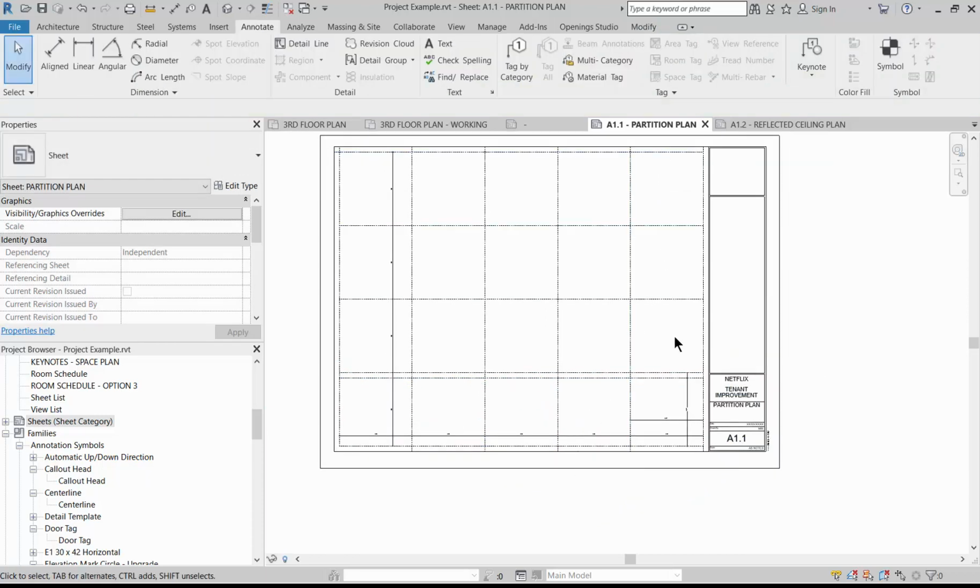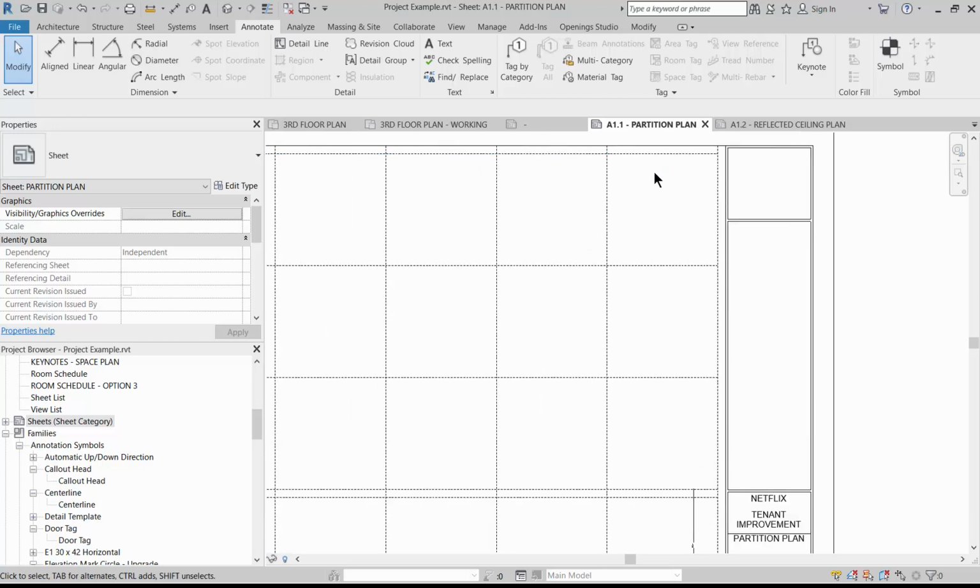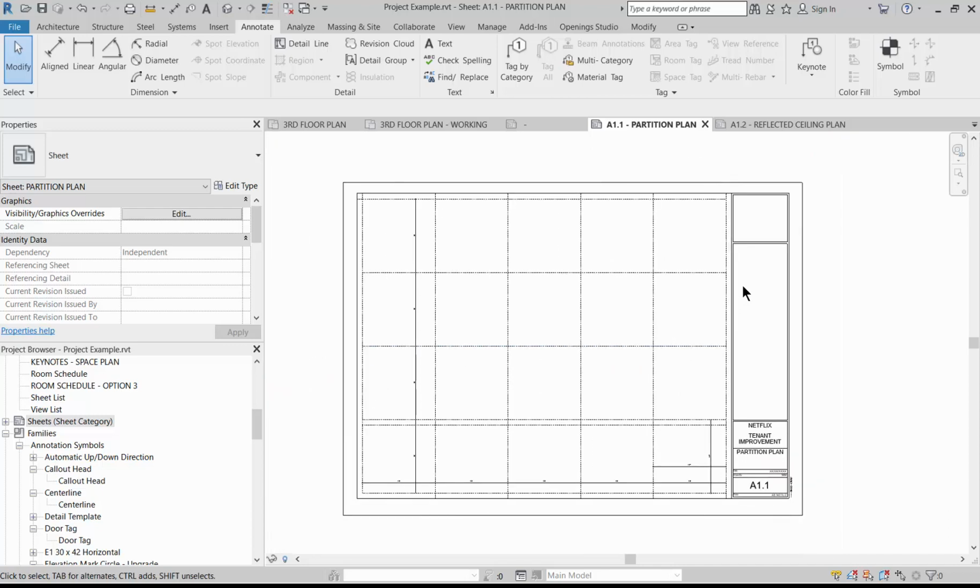If I'm putting them around the top, then I would create a 1/2 inch offset wherever I need to add a title. And then my actual plan view is going to go either horizontally with the notations along the bottom, or more vertically with the notations along the top, or somewhere within this area. I could even potentially have a vertical note block here and have 2 horizontal floor plans if my scale of my project is small enough that I can fit 2 floor plans on one sheet.